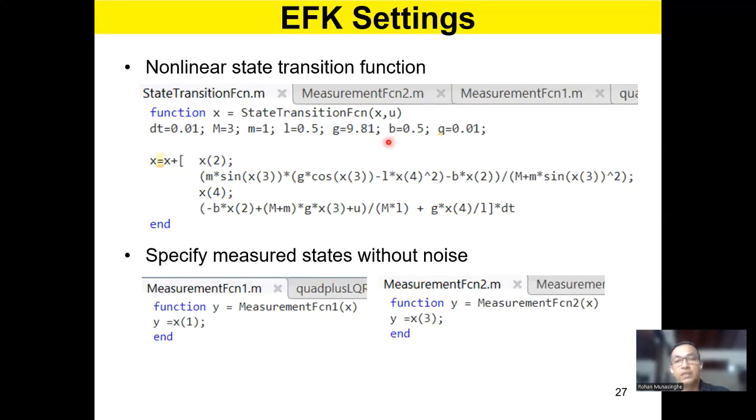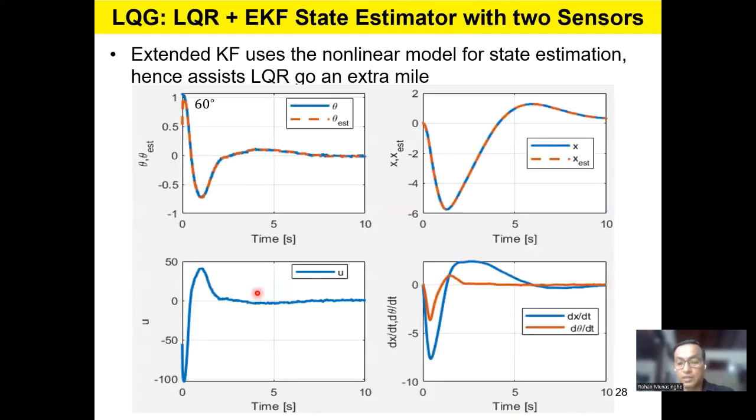You indicate in the Simulink extended Kalman filter block the state transition function, this name in the top page, right? And you write the MATLAB file and keep the file side by side with the main code, in the same folder. You have several M codes. So this is the rate of change, the Jacobian matrix of the plant. Okay, and the measurement function, right? And this is the result.